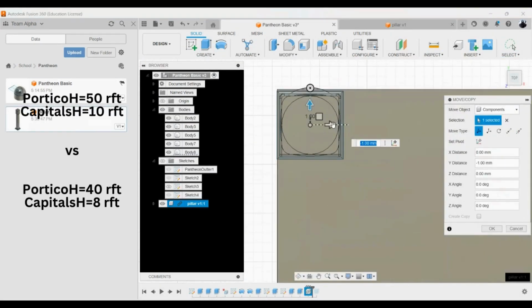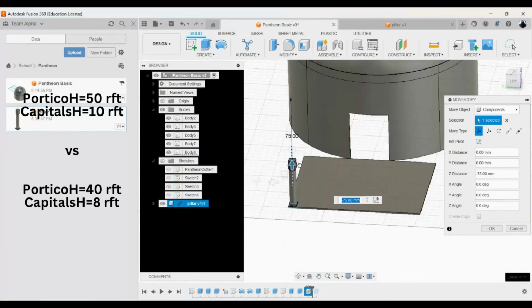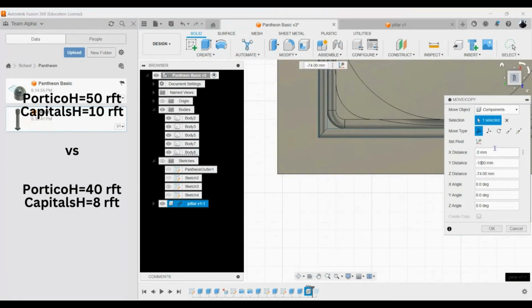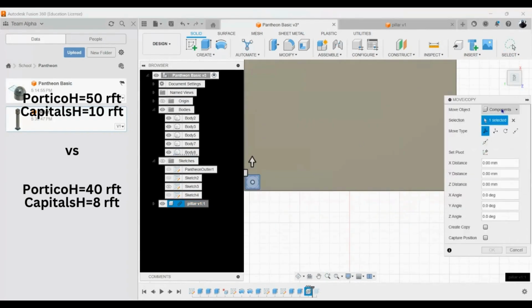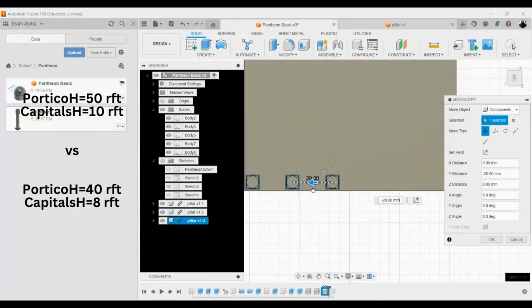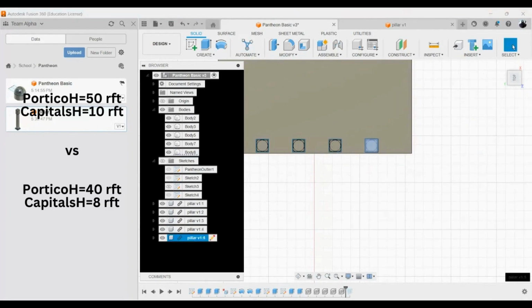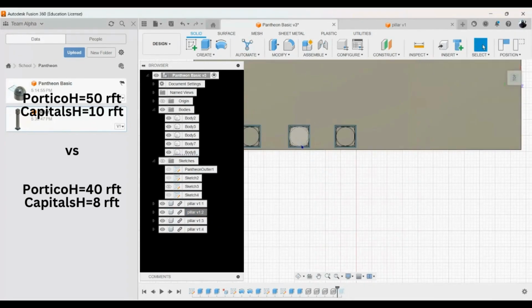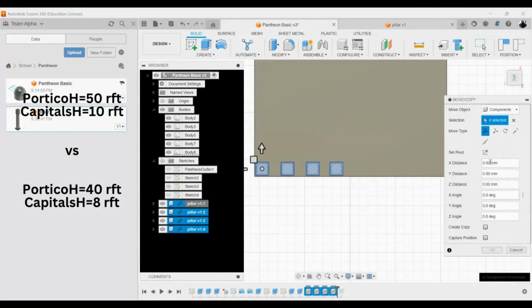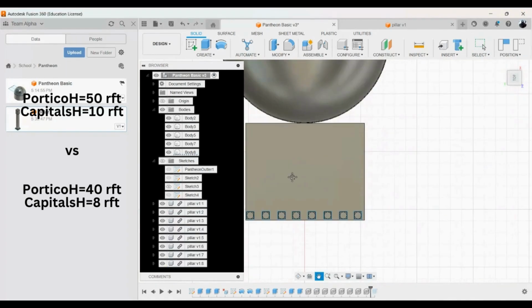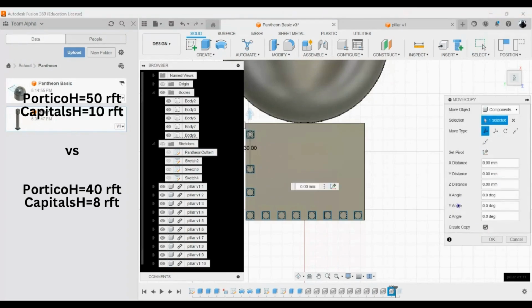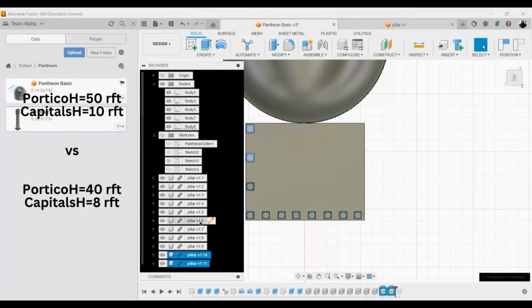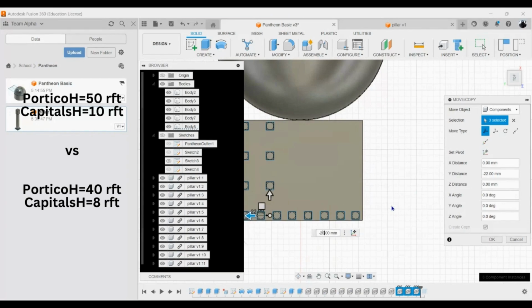On the intermediate block between the portico and the rotunda, the remains of a second pediment suggest that the existing portico is much shorter than originally intended. A portico lined with the second pediment will fit columns with shafts 50 Roman feet, or 14.8 meters tall, and capitals 10 Roman feet tall, or 3 meters, where the existing portico has shafts 40 Roman feet tall, 11.9 meters, and capitals 8 Roman feet, or 2.4 meters tall.